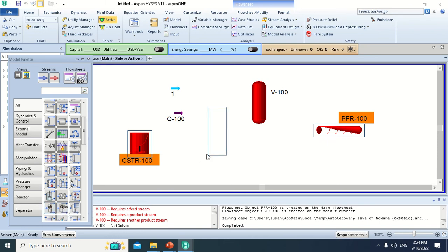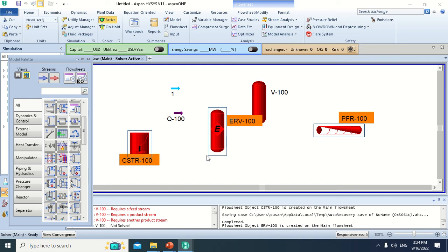This is the equilibrium reactor. The equilibrium reactor is a CSTR with a specialization in equilibrium reactions and thus can only function with reaction sets including that reaction type. The outlets from this reactor will be in a state of chemical and physical equilibrium according to parameters defined in the reaction set. As a consequence, the operation is extremely sensitive to input parameters and variables. The user might find it easier to use the Gibbs reactor in situations where sensitivity affects the program's ability to reach convergence.